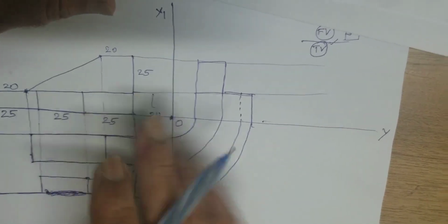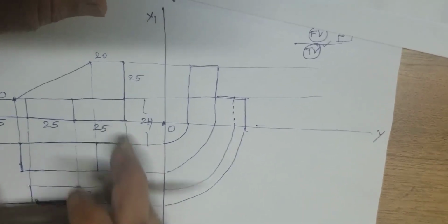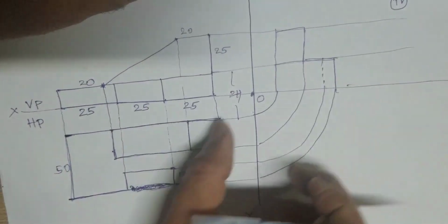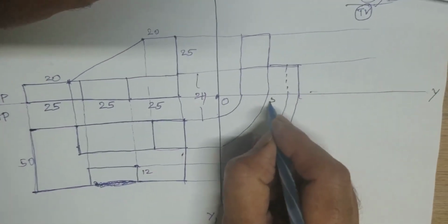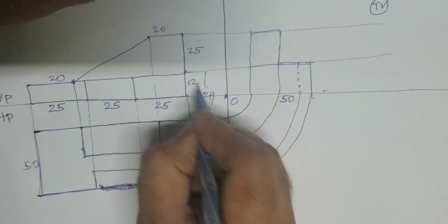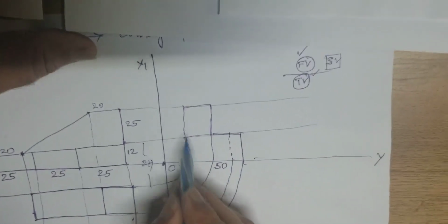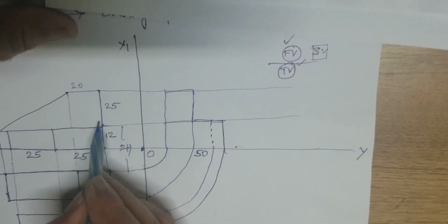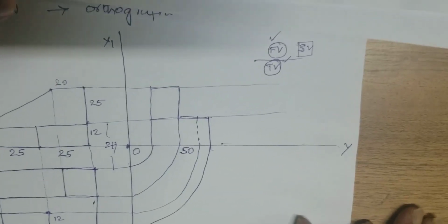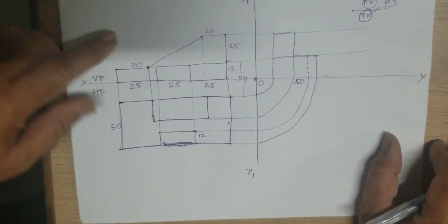So regarding the dimension, one place when you are indicating the dimensions, that is enough, because this is 75, no, this is already it is coming to 75. Regarding this 50, when you are coming in radius, it is also 50, no need to mark in fact. This is 25, once again 12, this is 12. So this is 12 and this is 25, no need to mark. If you mention here, the same dimension is also coming over here. That is how we have to write the orthographic view of a given isometric view.